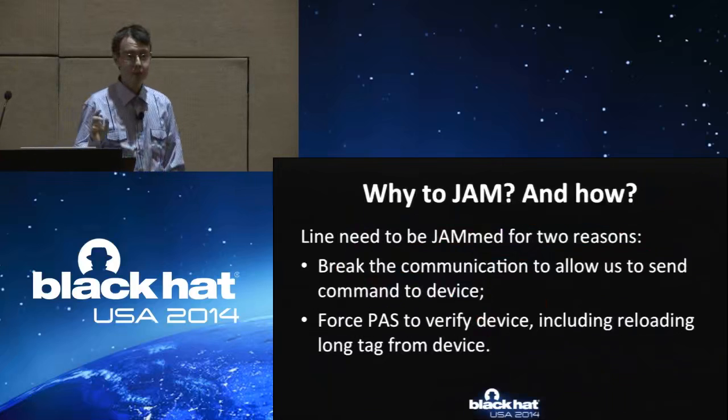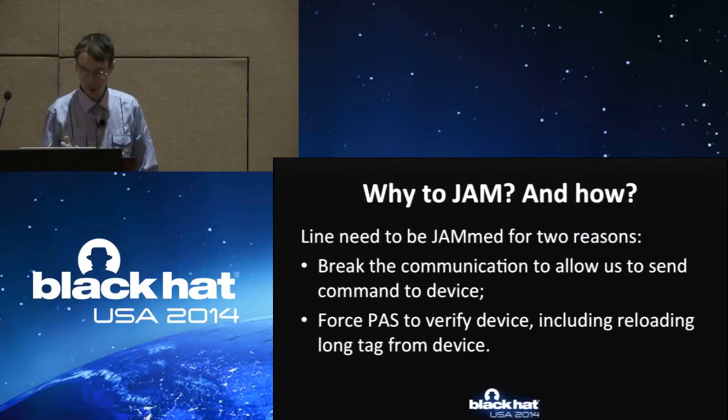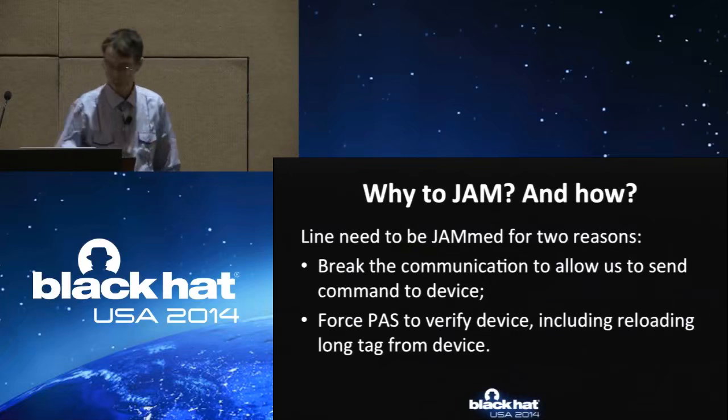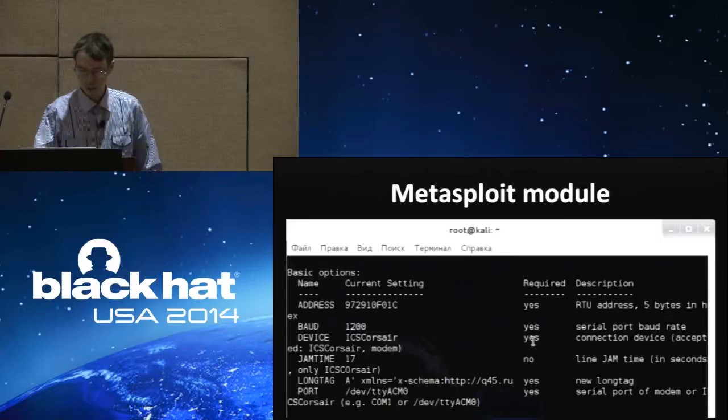Now I need to say why we're jamming the line. Remember that HART is a master-slave half-duplex protocol, so we should not interfere our change long tag command with other line traffic. We're jamming the line, and we're getting 2 profits from it. First, we're forcing devices to follow the standard and stop communication for a small amount of time. And also, we force the PAS system to verify devices after this time passes. And the PAS system will reload long tags.